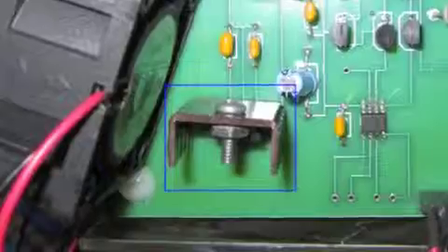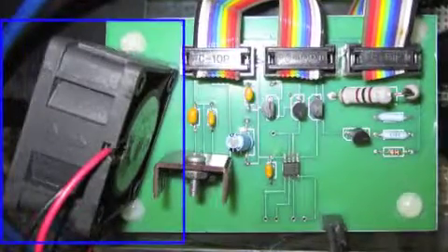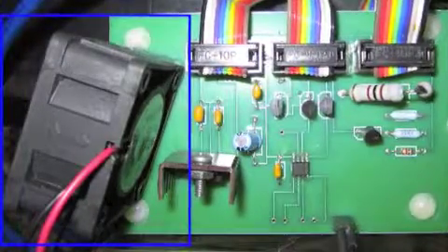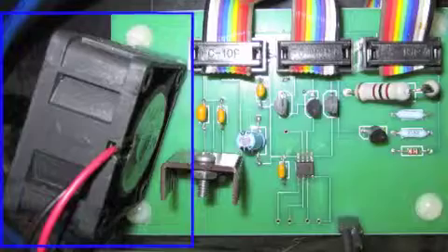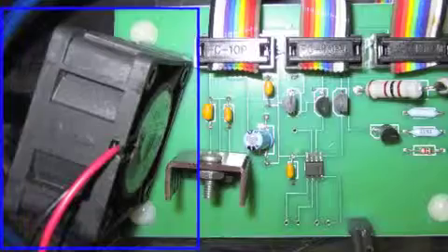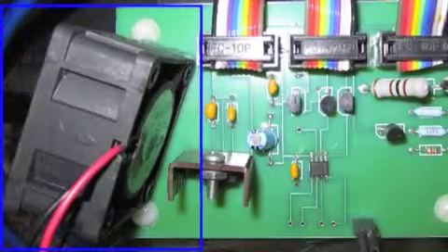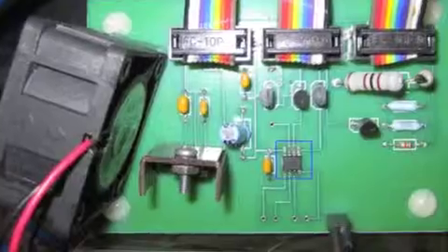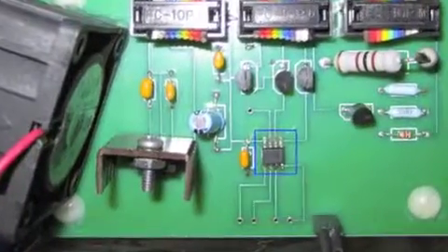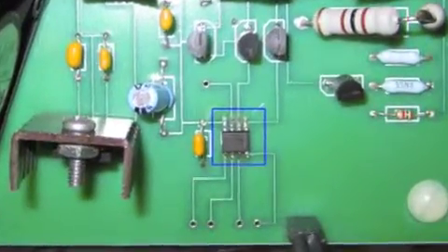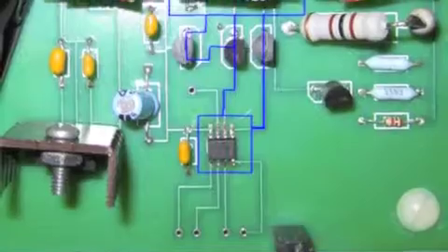used by the microcontroller. The temperature control circuit uses our 36 volt DC line, the VDD rail, to power a 12 volt fan turned on by an NPN transistor which is controlled by one of our AVR board's 5 volt lines. The airflow produced by the fan is intended as an overheat protection in case the power regulator circuit grows too warm. In order for the temperature control circuit to sense an overheat, our design includes a temperature sensor that uses I2C to communicate with the microcontroller. This sensor requires 3.3 volt power, which we supply with a separate regulator, and it communicates to the microcontroller using a data and clock line.